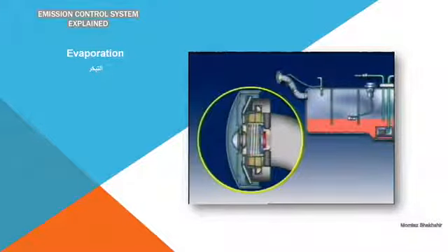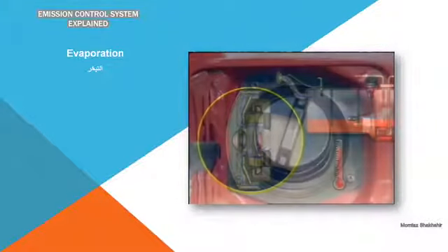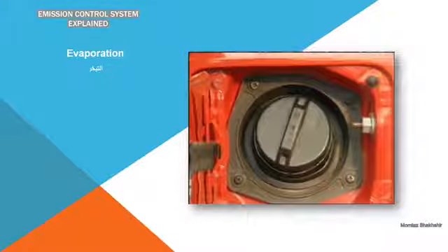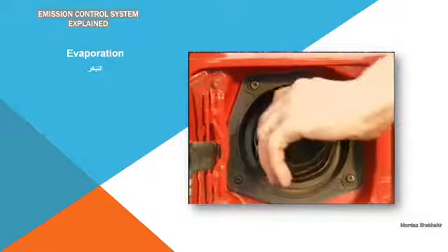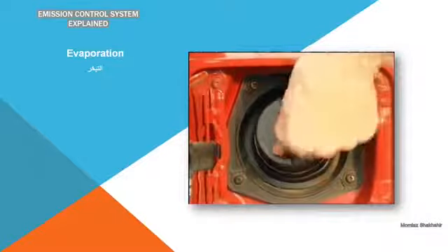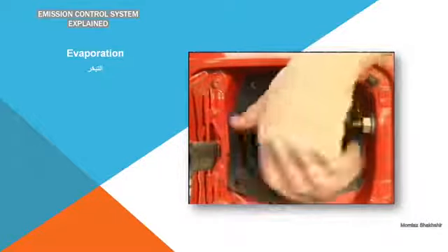The fuel cap may also incorporate a pressure relief valve. If the tank's internal pressure exceeds the set value of the relief valve, it can stop the tank from rupturing. Some modern caps have no valves at all and are completely sealed to stop the entry of air and water, as well as the emission of fuel vapor.